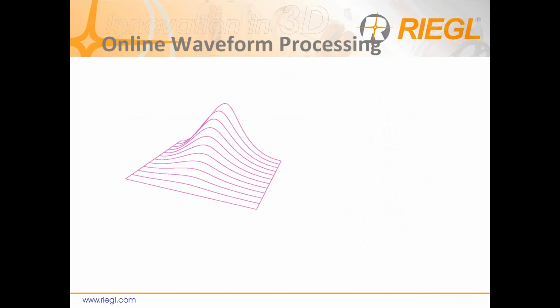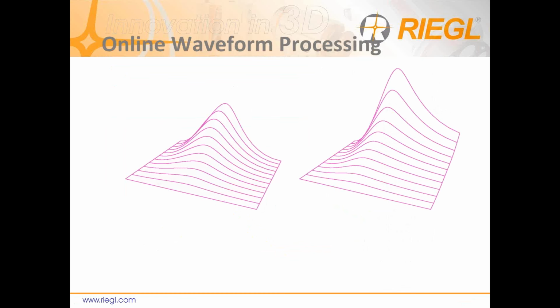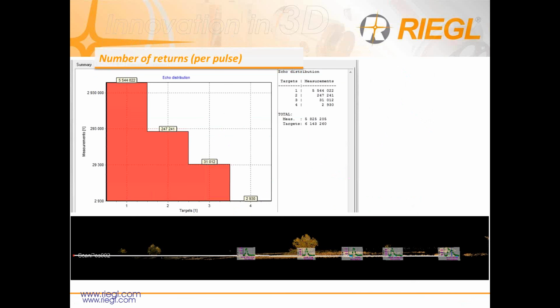Because I was asked to go into a bit more technical depth, I will. It's not quite as simple as just a 2D waveform. In principle, every scanner is unique. It has unique physical properties, unique electrical properties, and we have to calibrate for that. So we have basically a library of waveforms which cover quite a spatial domain depending on how the scanner is used and what it's doing. We calibrate all these applications, so all the dynamics of the system response, and we model that in 3D. And this is really what we're fitting over time. So it's a bit more complex. I won't go further than that just for the sake of time.